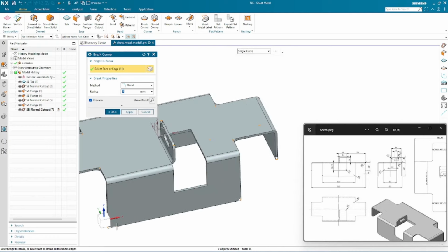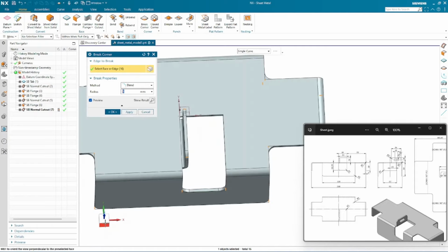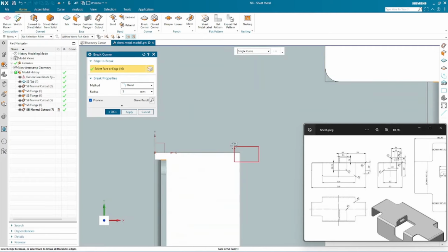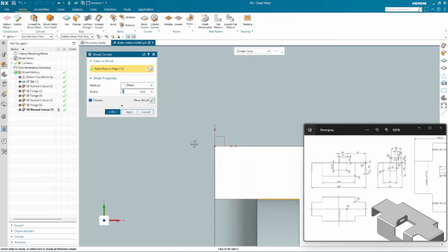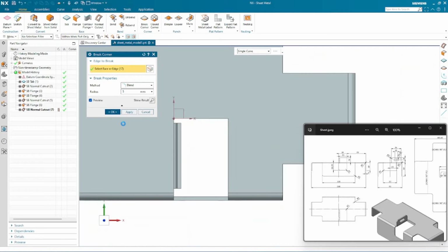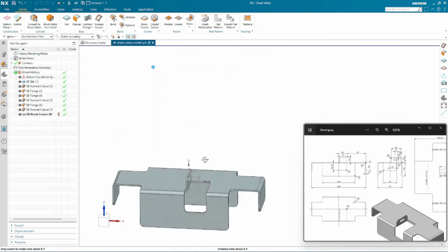There are also blends in the cutout. I can again use it, now I'll have to keep an eye on the bracket, how many edges it selects. Only one, then it's good. Similarly, top view, want this edge. I think there would not be enough space for this edge. We will see. Okay, click OK. My edges are done with the 5 millimeter radius.